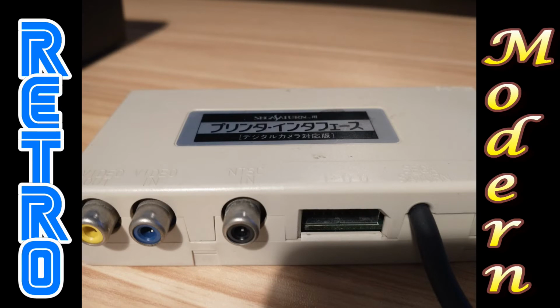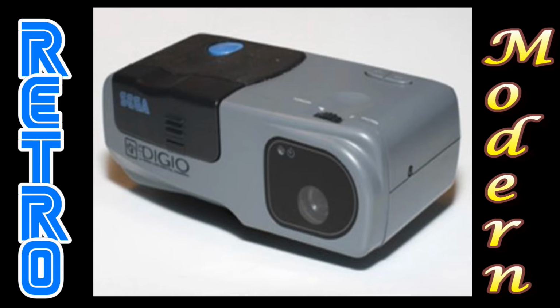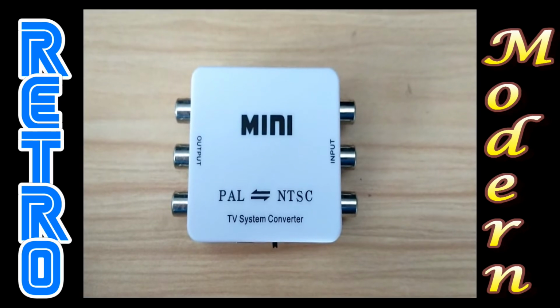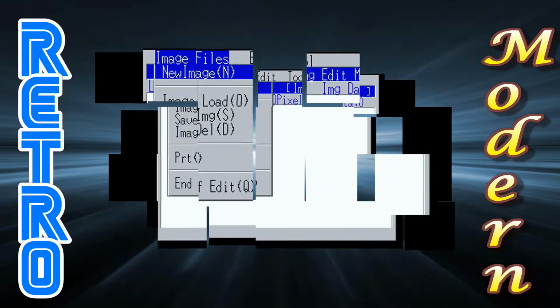If you look carefully at the printer interface where you connect the camera, it actually says that it's NTSC, so you are going to need a digital camera that does video out for NTSC, so from America or Japan. Now the recommended camera is the Sega Digio from Japan, but it will work with any camera from the 1990s, but you will have difficulty with PAL. Now you can use an NTSC to PAL adapter, but the quality isn't very good, which is what I used. You will get much better quality by using a digital camera from either America or Japan at the time.